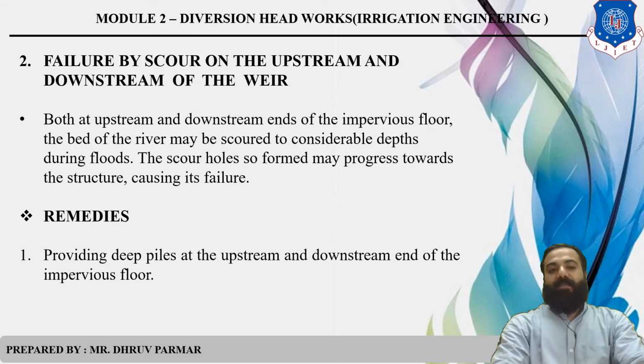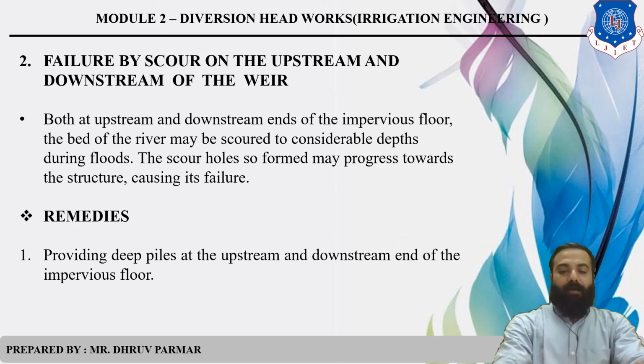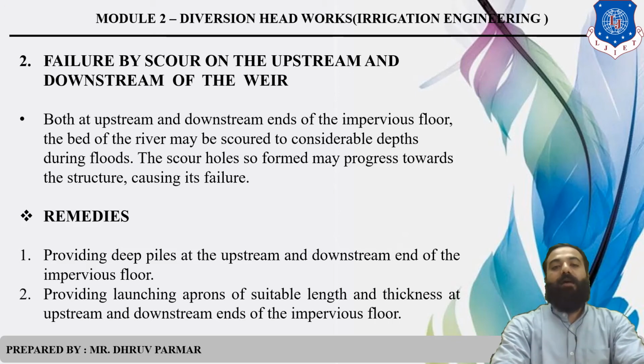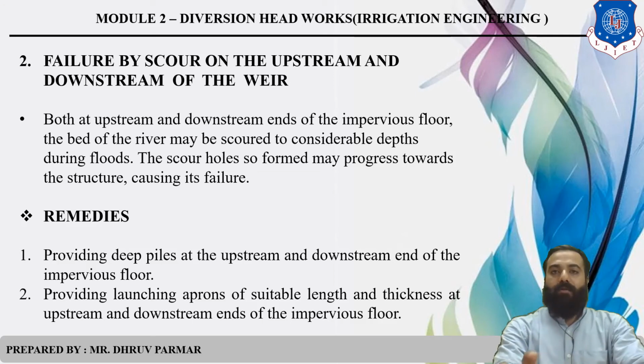So what are the remedies? First, deep piles are provided on the upstream and downstream side. Then, provide a launching apron of suitable length and thickness at the upstream and downstream ends of the impervious floor. So what is a launching apron? A launching apron is a type of structure used for dissipation of energy. Clear?